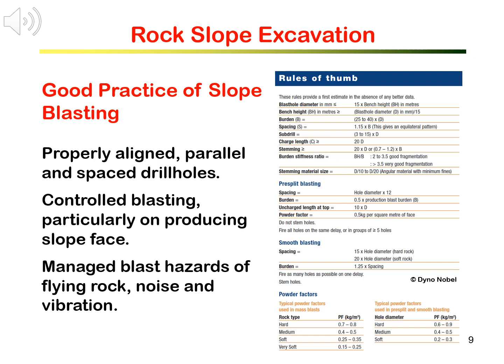In drilling the holes, make sure holes are properly aligned, equally spaced, and parallel. During drilling, the holes may deviate due to the influence of rock joints or long distance and become non-parallel. That will result in poor blast quality.